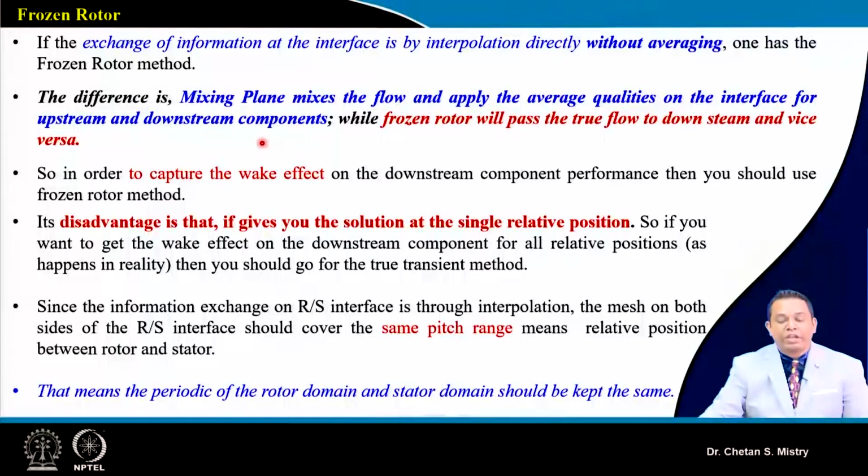The mixing plane was doing averaging at one plane, and that was transferred to the next domain, while the frozen rotor transfers the data straight away. Whatever data is captured at the exit of my rotor plane, the same data will be transferred to the stator.